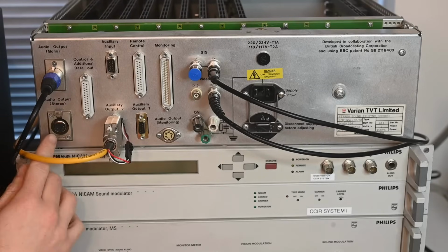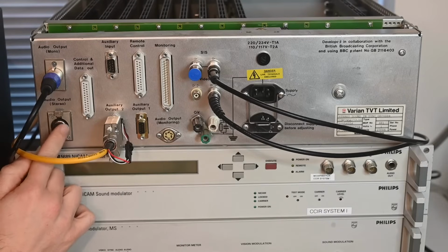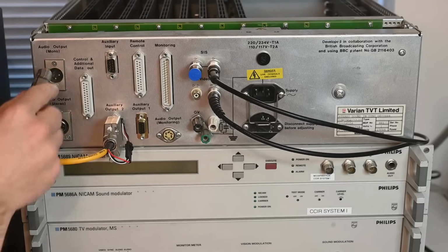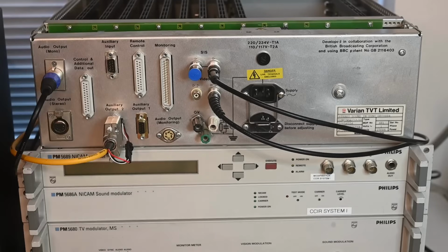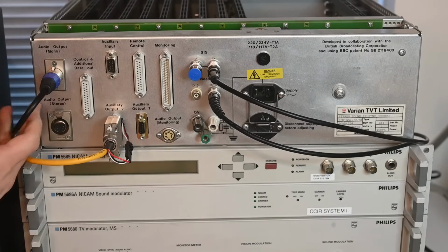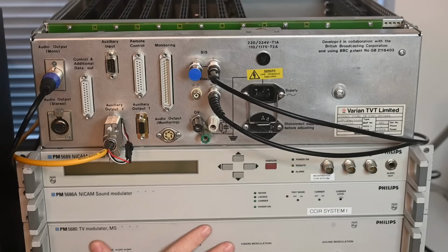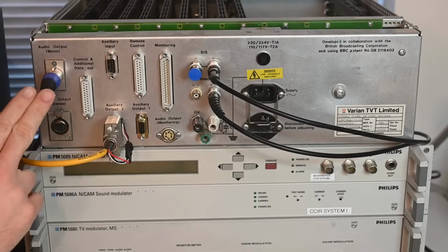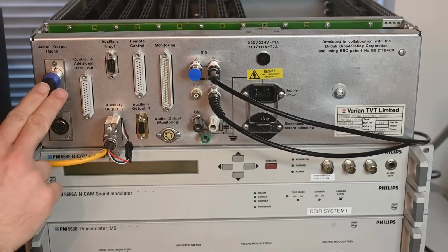However, you'll notice that there are some analog interfaces on here. So we have an audio stereo output, which is a 5-pin XLR socket. And we also have this audio output mono, and you'll notice that's a 3-pin XLR, so that's just a standard connection there. What this is used for is the FM mono on the modulator, and this is another thing you might not know about NICAM in the United Kingdom, is that even if you didn't have a NICAM capable receiver, your audio was actually coming to you via NICAM anyway through this equipment. It's just that the NICAM was stripped off and converted into a mono audio signal at the transmitter, which is what your low-cost equipment is actually receiving.